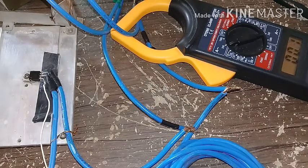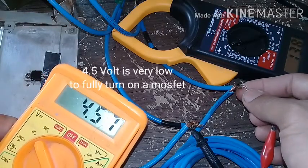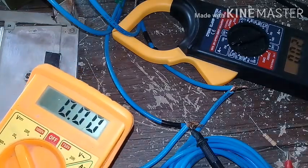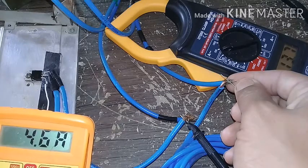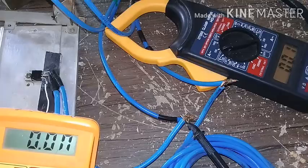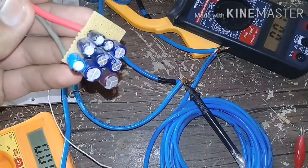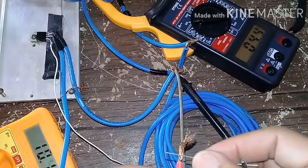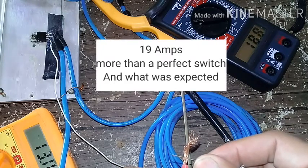The reason this is happening is the gate voltage. When the MOSFET turns on, it will draw a large amount of current, which will cause a voltage drop. And because the gate voltage is from the same power supply, it will drop too, causing a high resistance between drain and source. The solution for that is a capacitor bank. The only problem is this.